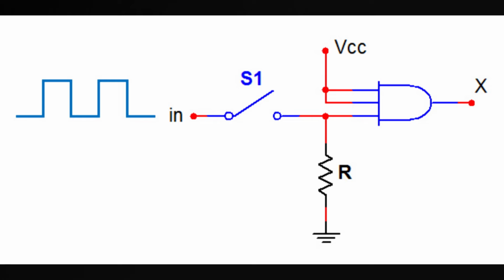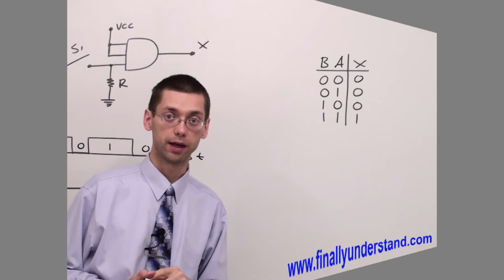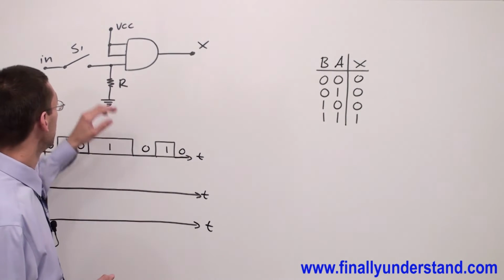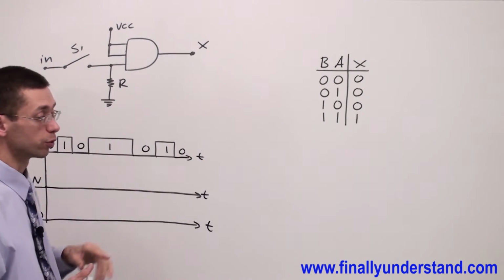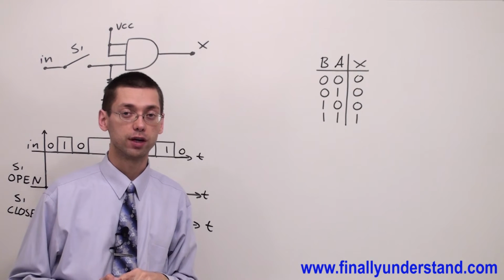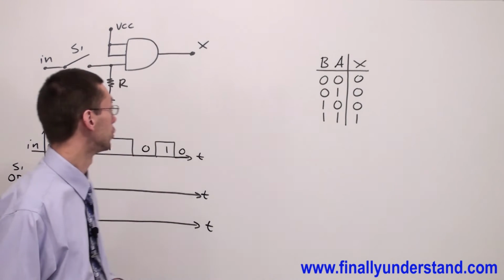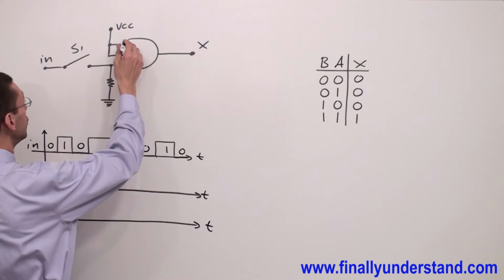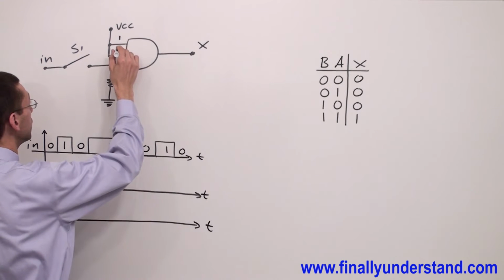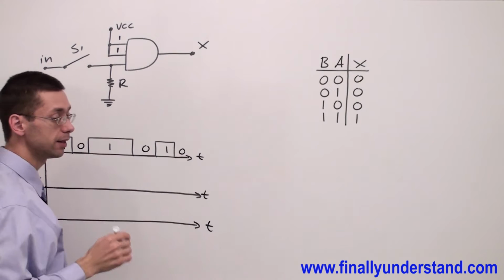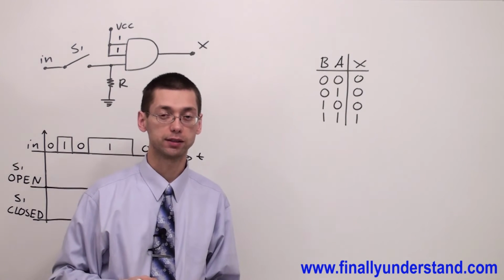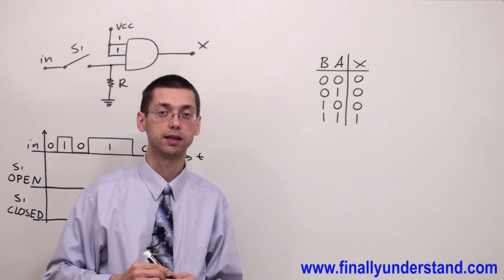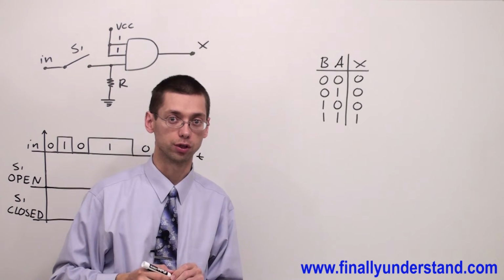We have another example on the board. This time we have a circuit with a 3 input AND gate. Please notice that the first 2 inputs of this AND gate are connected to VCC. Don't think too long. These 2 inputs are going to receive logic 1s. Anytime you have an input connected directly to VCC, that input is going to carry logic 1.